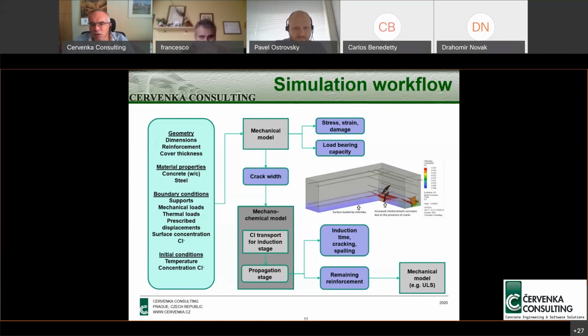We say, what is important for our structure? For our structure, it is typically not so important that a small 2 centimeter piece of concrete separated and is missing. What is more important is that now the corrosion rate increases. So we consider in our model the fact that at some point the spalling must have occurred, because we know the cover depth and we know the time of the corrosion process.